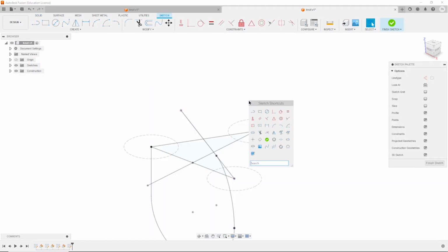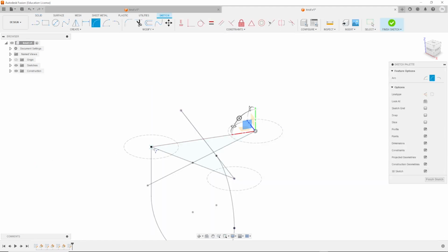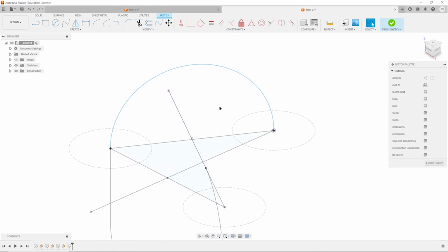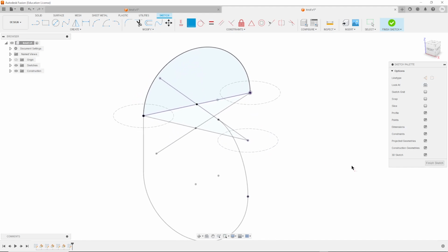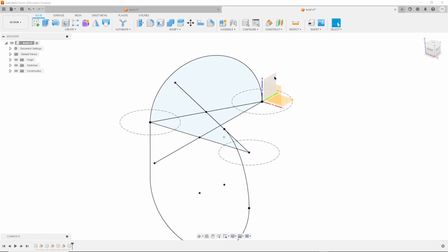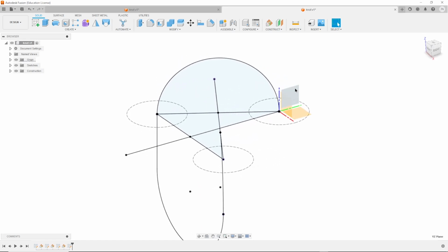Create that sketch, take that 3-point arc, connect that over here, connect that there, drop that here, and place that on that line, fully constrained. Great. And well, one more time. Or actually, we can take that plane we get right here.